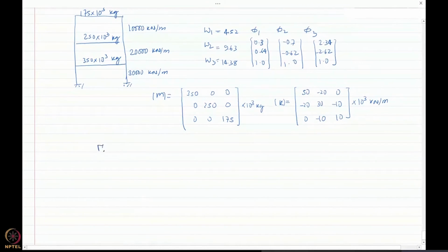How do we do that? Through the modal participation vector. This is the vector that establishes the relationship between your single degree of freedom system and the multi-degree of freedom system for which you actually want to find the response. You already know the expression for this. It is phi n transpose S, where for seismic excitation S becomes mass times the influence vector, divided by Mn.